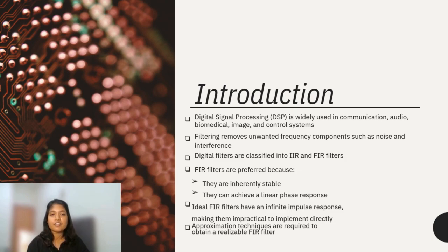In this project, the focus is on the FIR filter because they are inherently stable and capable of achieving a linear phase response, which is especially important in applications such as audio and image processing, where the signal's distortion must be minimized. However, an ideal FIR filter has an infinite impulse response, which makes it impractical to implement directly. Therefore, approximation techniques are required to obtain a reliable filter. One commonly used approach is the windowing method, which is the main technique used in this project.